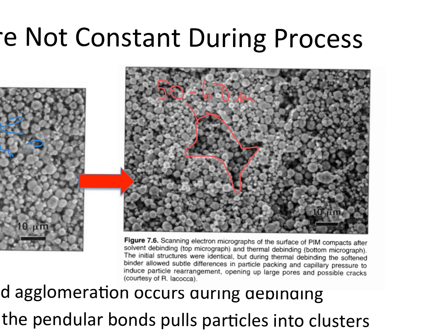Right, so the liquid forms, it pulls particles close together. It doesn't mean that everything is being pulled. So what happens is the microstructure retreats away from itself, or it's being pulled apart. And you might think, well, maybe sintering will fix this. No, sintering will make it worse. So these areas will pull toward each other during sintering, and that pore will become even larger as a result. So you catalyze the pore formation because you don't control capillary forces, and things just get worse from there.